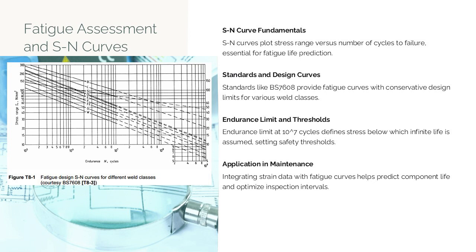By integrating strain measurements with fatigue curves, engineers can accurately predict component life, optimize inspection intervals, and implement design improvements. This approach is vital for high-stress environments such as power plants, offshore platforms, and heavy machinery, where fatigue can lead to costly downtime or hazardous incidents.